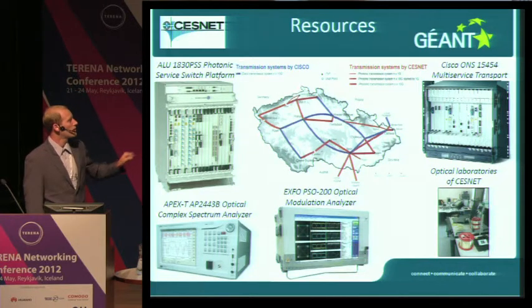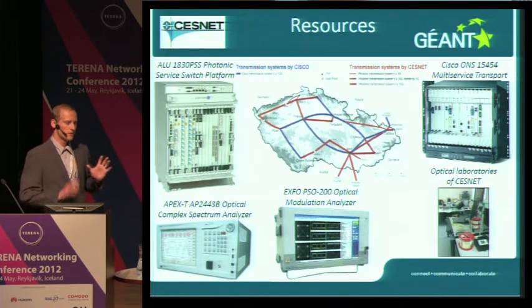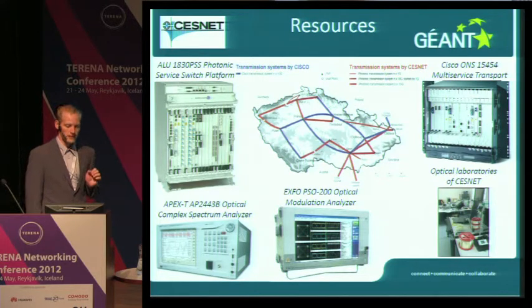From the laboratory equipment, I would like to highlight two devices here. The first one is the optical complex spectrum analyzer from Apex Technologies. I am talking about it because its resolution is about 5 megahertz, so you can actually see more on those optical spectra than you could with standard telecommunication spectrum analyzers. Then we also got, for these tests, an XFO optical modulation analyzer, so you will be able to see constellation diagrams of optical coherent modulation.